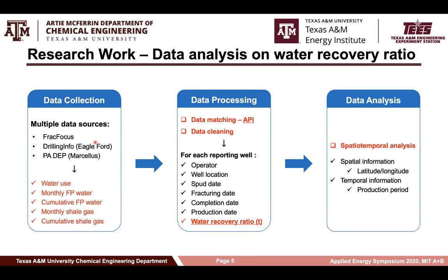And the FracFocus database shown here was used to collect water use data. To integrate the well data from different sources, we used the API number, which can be used for well identification, to match the water use and flowback and produced water data for each reporting well. After the data cleaning, where we checked and removed the duplicates and meaningless values, the listing information for each specific well was obtained, and the water recovery ratio data were calculated.